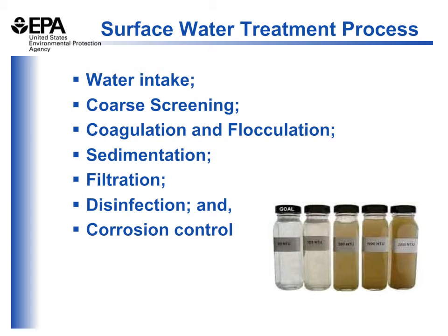The surface water treatment process includes 7 steps. The first is the water intake, which we've covered on the previous slide. Water that's coming in through the intake then runs through a screen to minimize the debris that may be within the system. There's a series of steps then to remove the particles and the chemicals that may be in the water, which we'll cover with coagulation and flocculation, as well as sedimentation and filtration. Once the water is treated, it is disinfected, and at that point, if necessary, corrosion control chemicals are added to neutralize the pH or minimize the acid within the water.